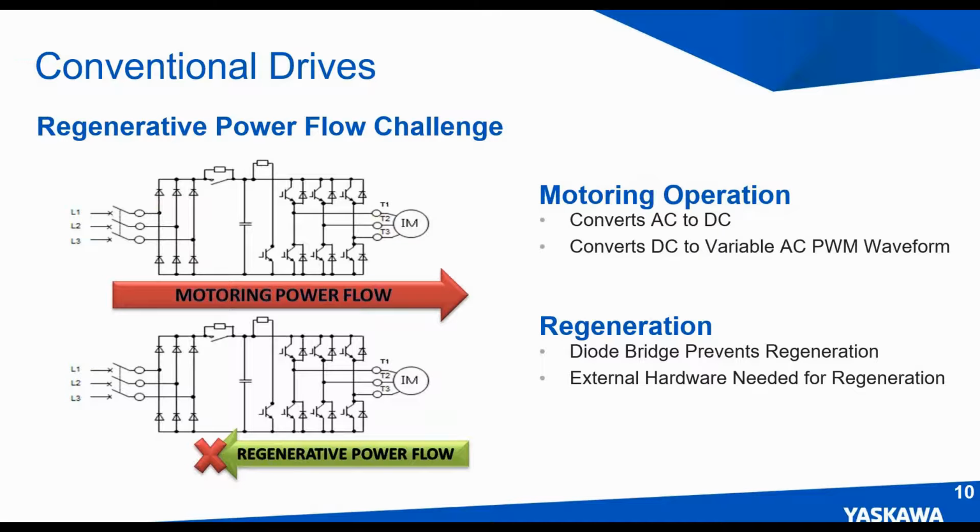So it can become commonly confused that drives can handle some sort of regen. It's not really true. Any regen these drives can absorb is really due to system losses: motor losses, mechanical losses, drive losses. Typically about 10 to 20% of the system rating can be handled by the overall system. It's when you go beyond this that you need to be able to dissipate that extra energy.